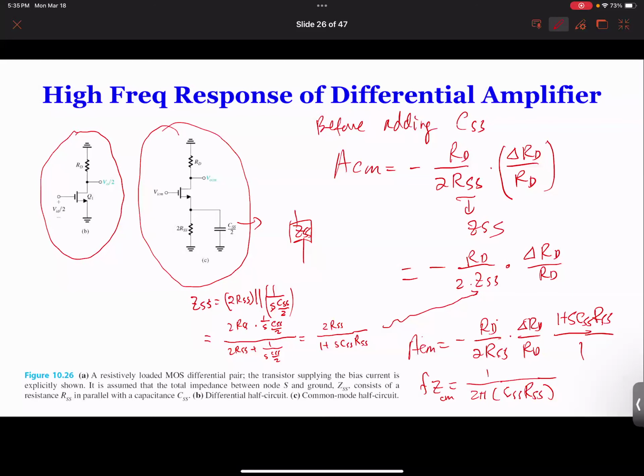So when you are designing the simulations, you can try different parameters, and you can see how your common mode and differential mode are going to change. Now for the simulation, apparently when you put up two R_Ds, they're going to be the same. So for your common mode, you can click on one of them and put 10 kilo ohm, for example, and put 10.1 on the other. Now you can see the common mode output. This is very easy to do in simulation. In real life they're always different, but in simulation you can manipulate the numbers to see the output.